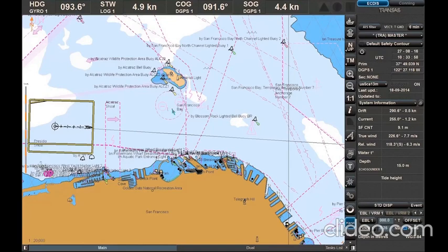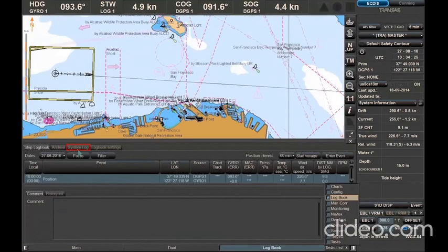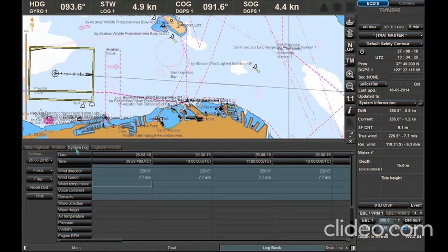System log. The system log is a file where both navigational and system events are automatically recorded. This is the mandatory electronic system logbook for an ECDIS, according to the IMO requirements. To access the system log, click on the Tasks List menu, select Logbook, and switch to System Log page. It should be noted that it is not possible to change any given data.